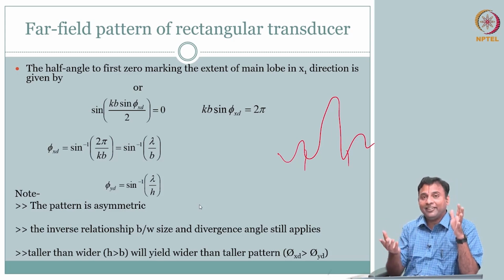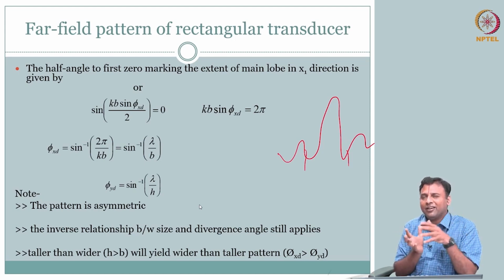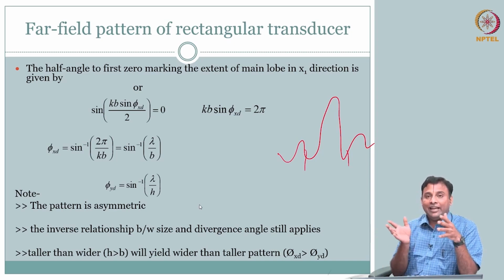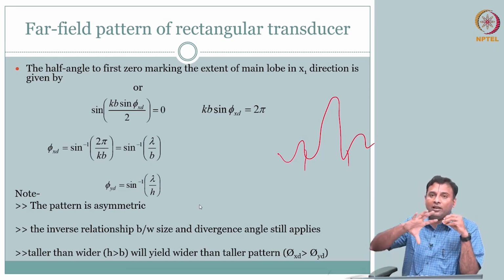When we cover imaging, we will explicitly address that, but even before that, you should intuitively start to think: what is the disadvantage of having a large transducer? Well, we talked about it: what we are receiving is a surface integral. That means you are going to get signal from a larger volume.